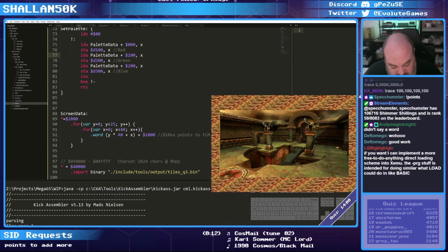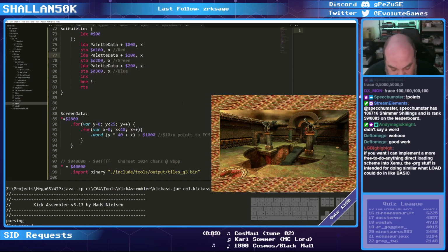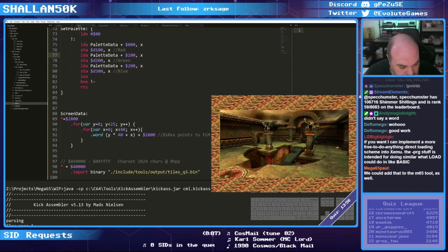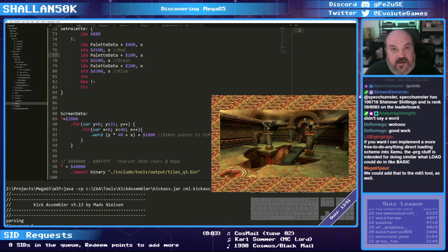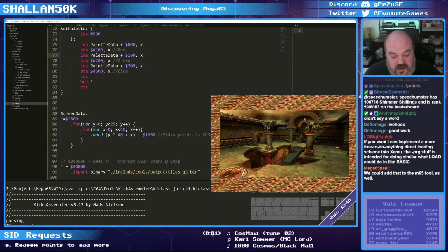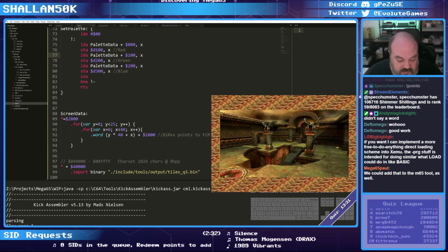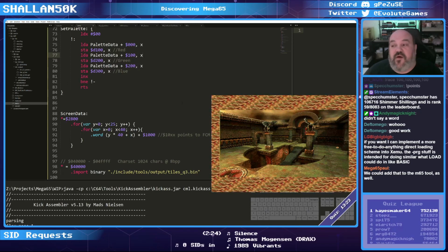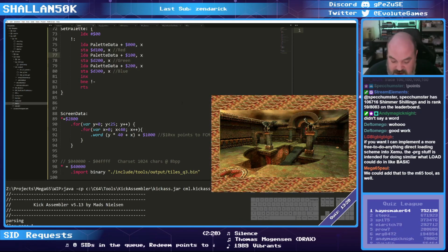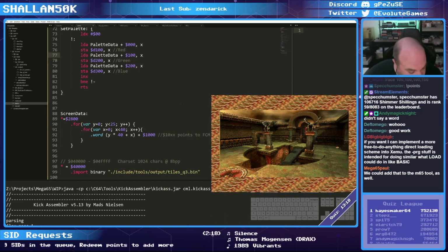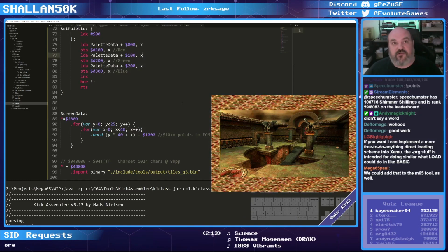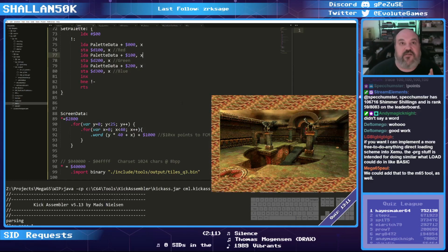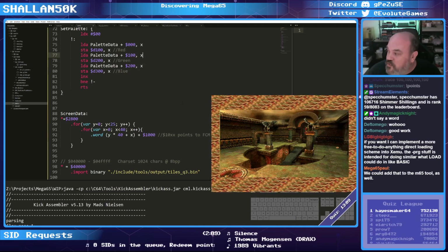Full color character mode, as I explained, is 64 bytes per character. Each byte defines a color in the 256 color palette, because you've got 0 to 255. Now, obviously, 64 bytes is a lot. So one of the things that the full color character mode requires is the use of 16-bit character locations. So what that means is the screen RAM here is actually using 2 bytes for every single character.